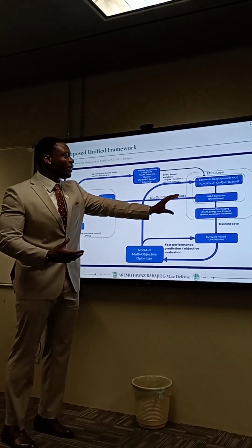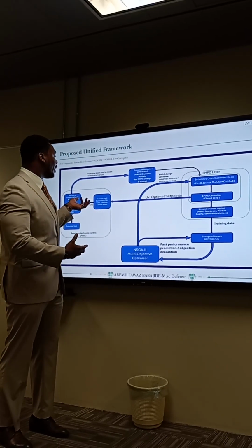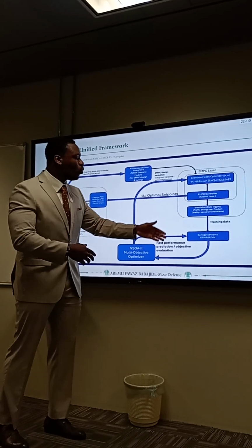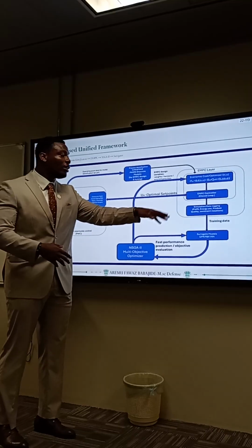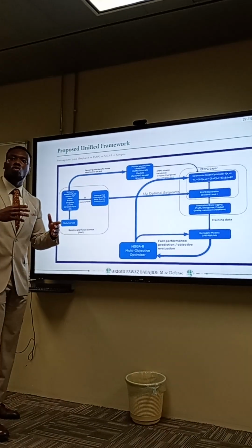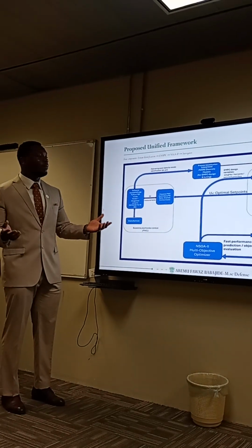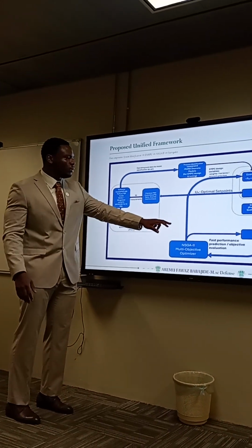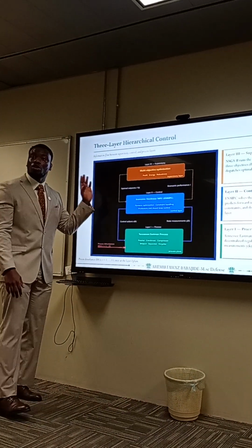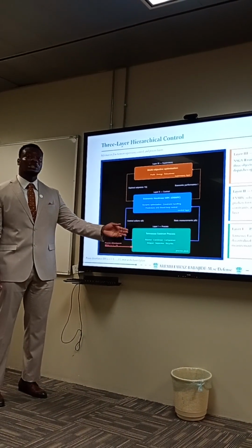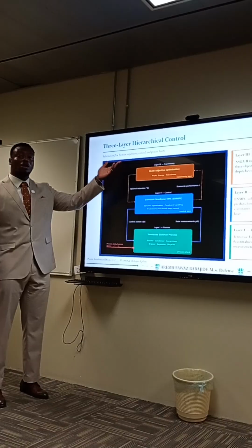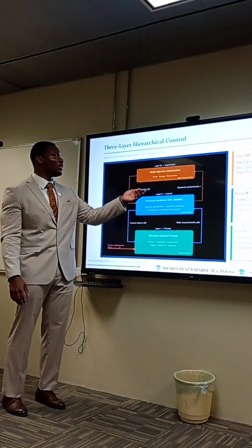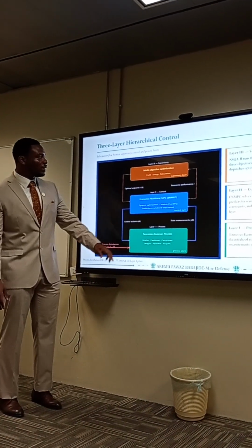And when you have an EMPC layer, you want one that's functional, that works, and that can operate the plant optimally in some given sense. Then over time, you want a multi-objective layer to run the plant on 3 different objectives, depending on what the plant or whoever is in charge of the business would prefer. Maybe they're trying to prioritize profit, energy, or quality. We'll see that in a second. Now we shrink that into just 3 blocks: you can see we have the Tennessee Eastman process, then the economic nonlinear MPC, and then the multi-objective optimization, which we split into 3 objectives: profit, energy, and robustness. And that's that.